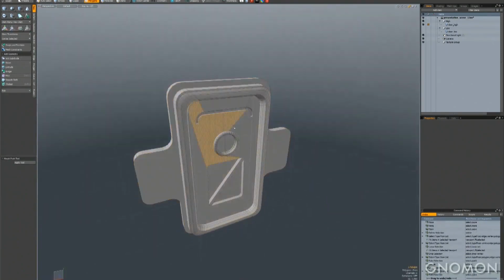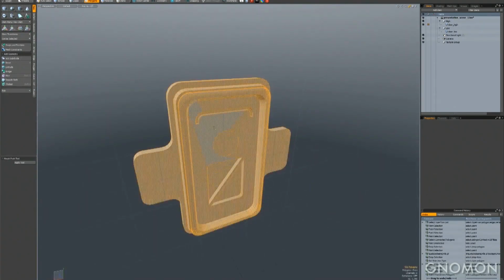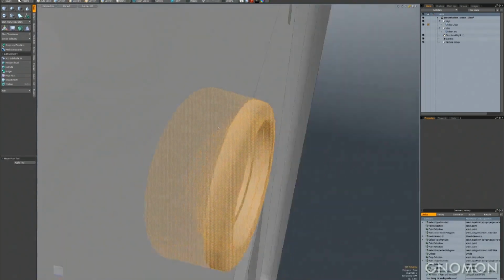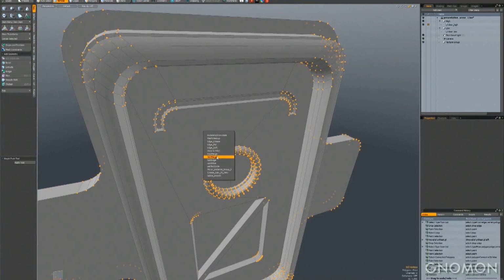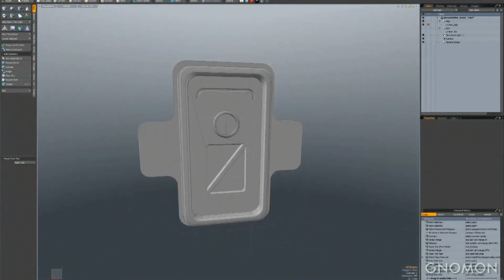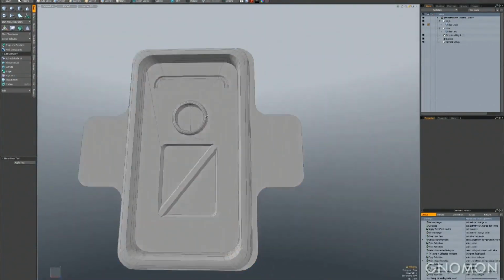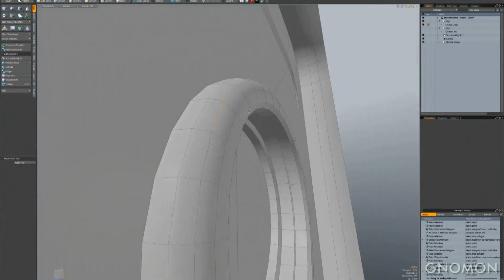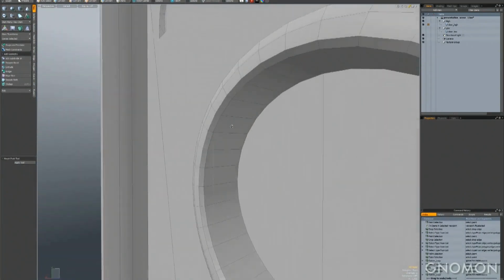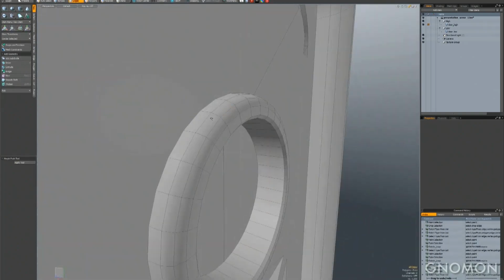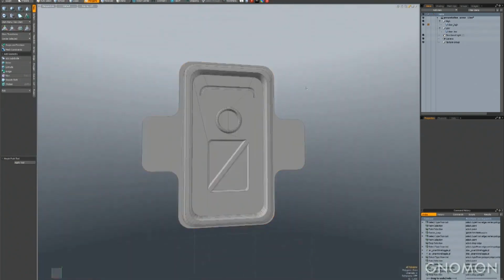We'll take this and do a quick additive Boolean. Nothing got ruined there. The geometry is all preserved. Everything is still perfectly functional. We'll weld those verts together to create one solid, airtight mesh, and delete these final two edges right here to finish our low poly out. And that's it right there. That's going to work for our low poly.